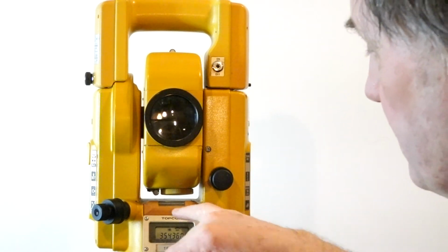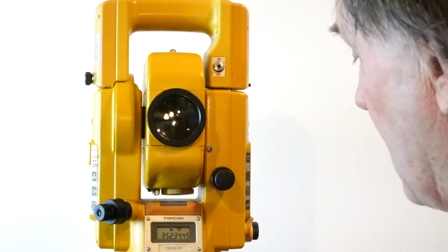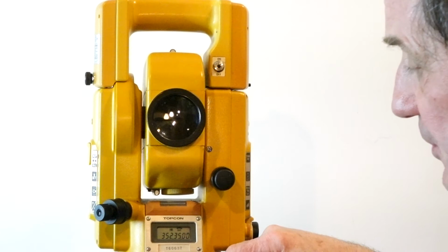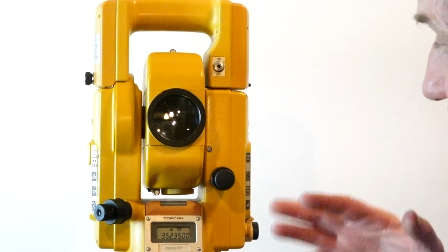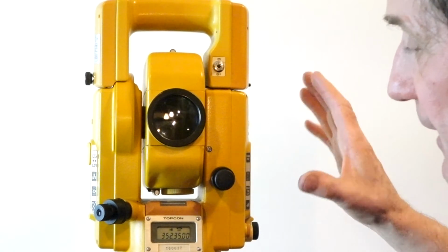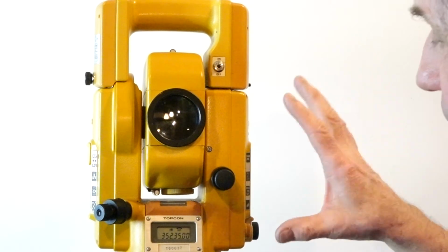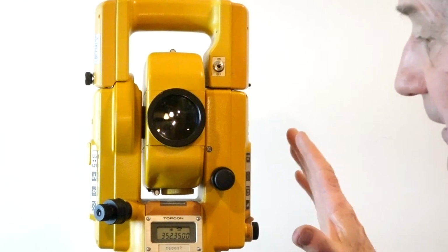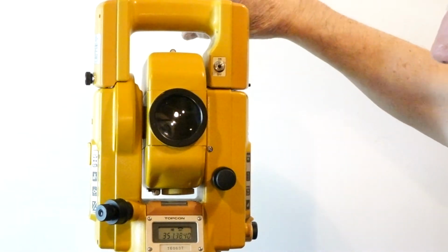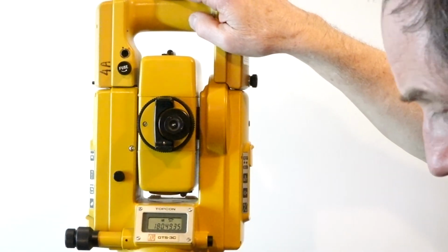It's very critical. There's a little bubble level in here that gives you 30 seconds per division. And there's also a circular bubble level in here. If you're not very close to having it set up to the center, it just won't read out. There's a compensator in this thing too, but it's not quite as accurate as the auto level. But the nice thing about the total station is it won't give you readings unless you're close to having this thing level. So it's pretty much foolproof. It's very hard to really mess up with this thing.